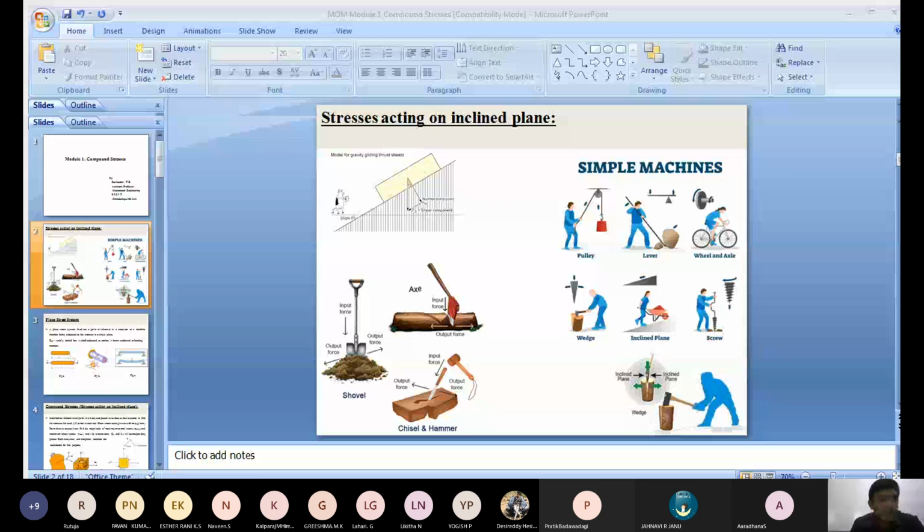For a best example, consider a bar. If an axial load acts on that bar, meaning only one load is acting, then you get only one stress, the normal stress acting on the component. Then you can easily determine the maximum stress induced in the bar. A bar subject to only an axial load, throughout its length you can pass an arbitrary cutting plane perpendicular to the axis.